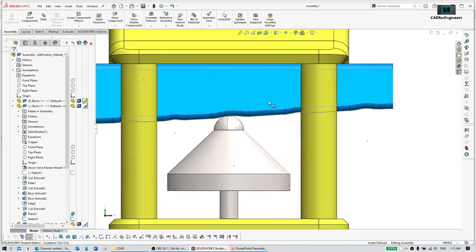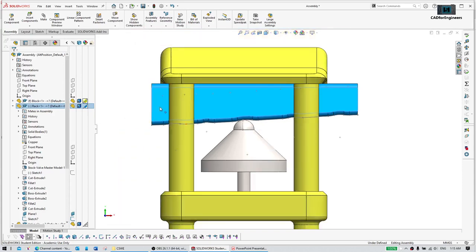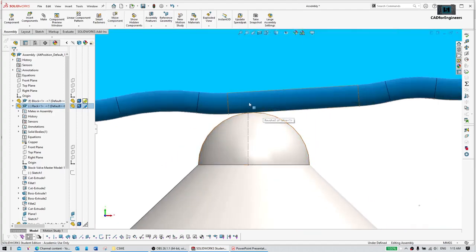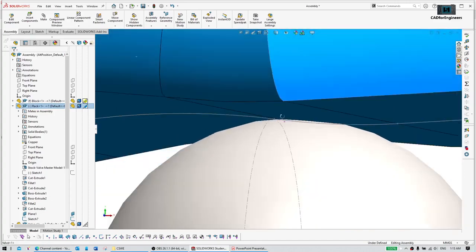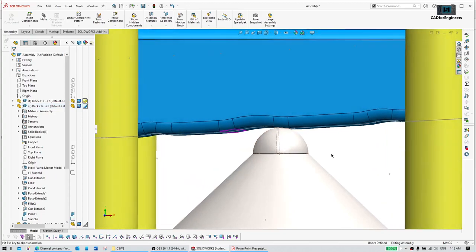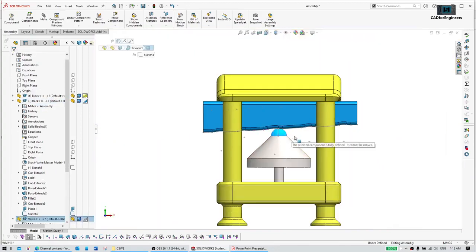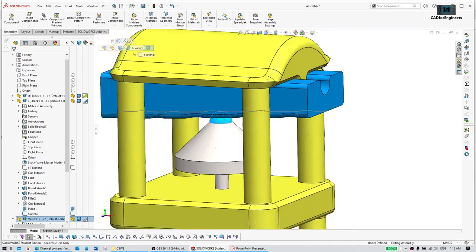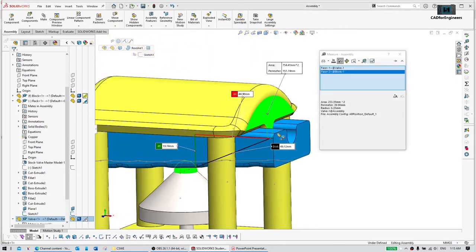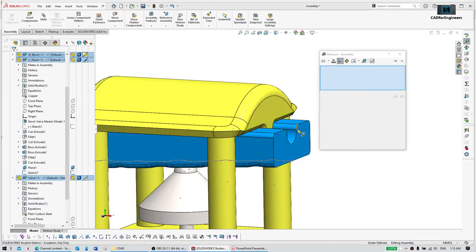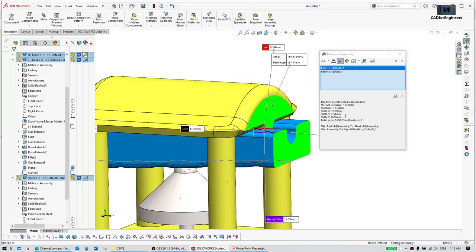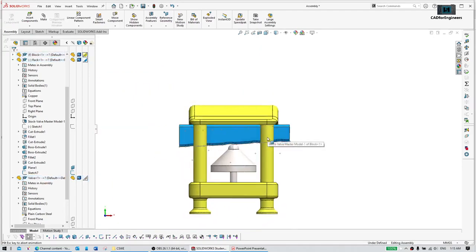Okay, let's try to drag this all the way to the right side and try to see. You see it doesn't go right now. I'm gonna go ahead and check one more time. Okay, it stops over here. Actually it stops over there. So if it stops over there, we can't do anything, right? Therefore we need to measure the distance between this face and also, let's say, this face. So the distance, let's just delete that and use it properly. Okay, the distance, for example, is 13.09, but in this case it doesn't matter. The method is what's important that I want to show you.